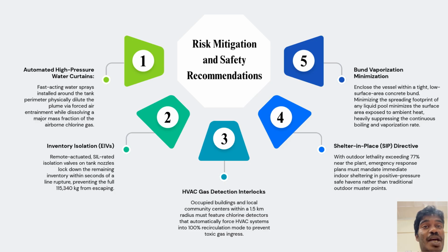On the administrative side, our primary directive is strict shelter in place. All occupied facilities within a 1.5 km radius must be equipped with toxic gas detectors that instantly interlock with HVAC dampers. The moment a leak registers, outside air intakes seal completely, transforming standard buildings into positive pressure survival havens.